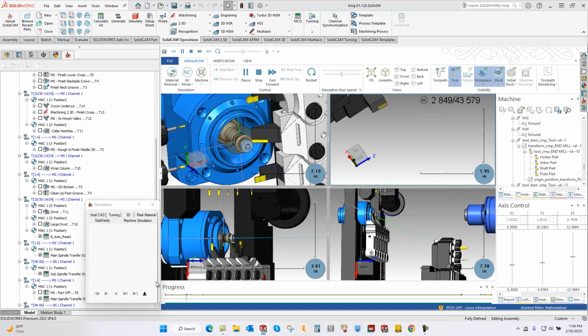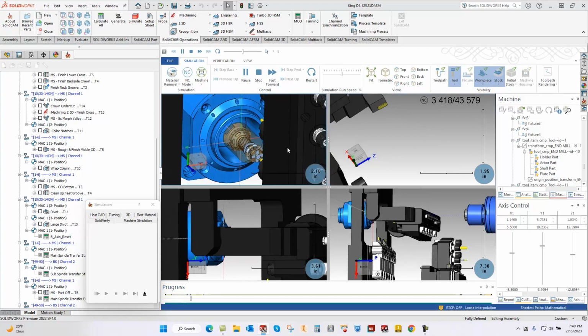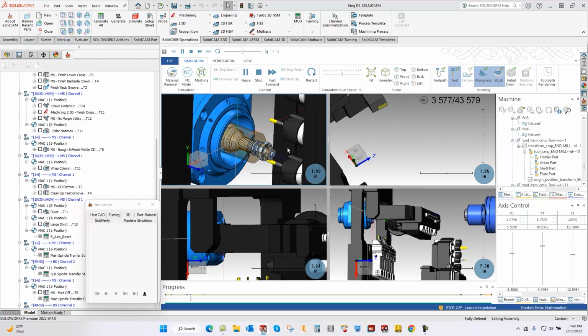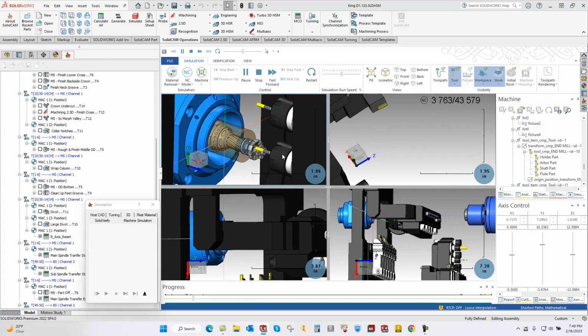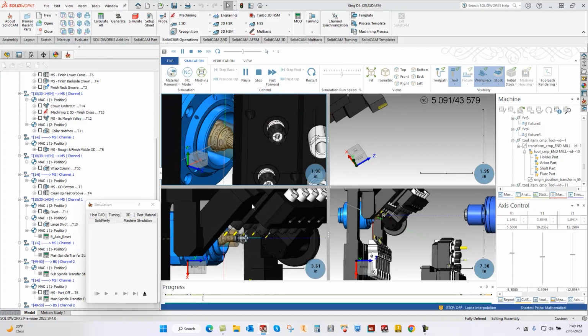Now, down here, you've got a play bar. These are the different operations. You can see it playing. If there's a long one, like this is the 5-axis cut. This is a simple swarf cut there. But after this iMachining toolpath, it's going to start doing a 5-axis simultaneous surface cut on these crown valleys here.